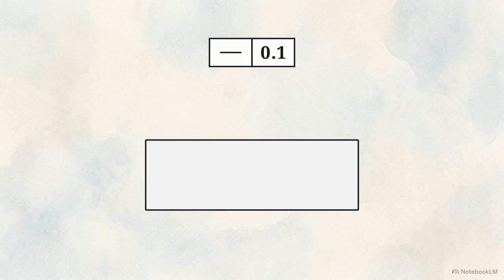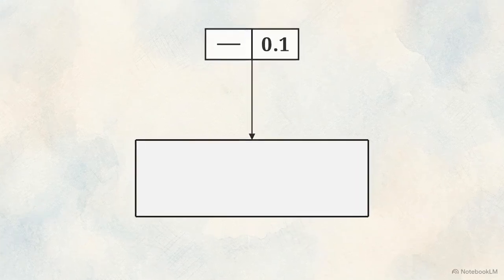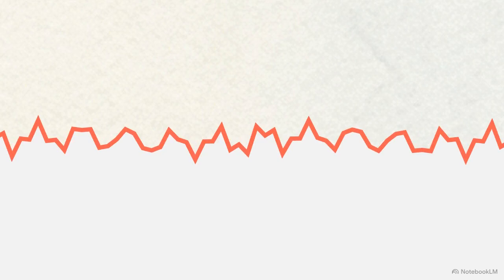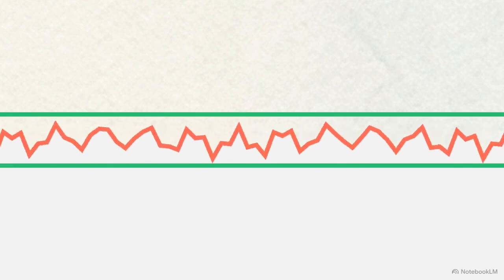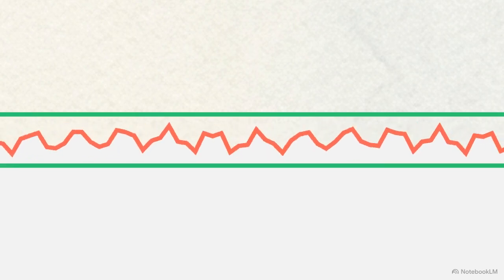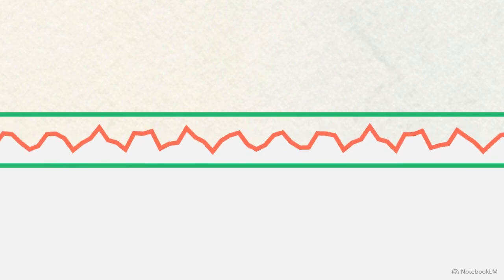When controlling the exterior of a part, the drafting syntax is highly specific. The leader line extending from the feature control frame must terminate directly on the surface profile line of the drawing. This creates a two-dimensional tolerance zone. The true surface of the manufactured part will always be slightly jagged. Every individual line element along that surface must fall entirely between these two perfectly straight parallel boundaries.